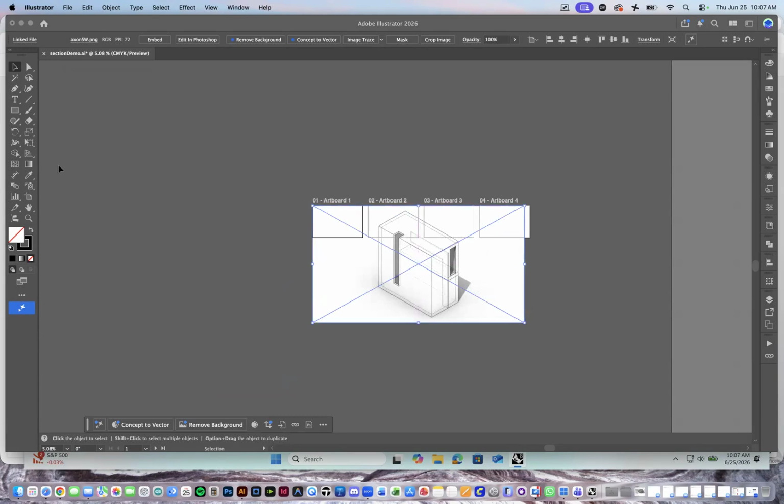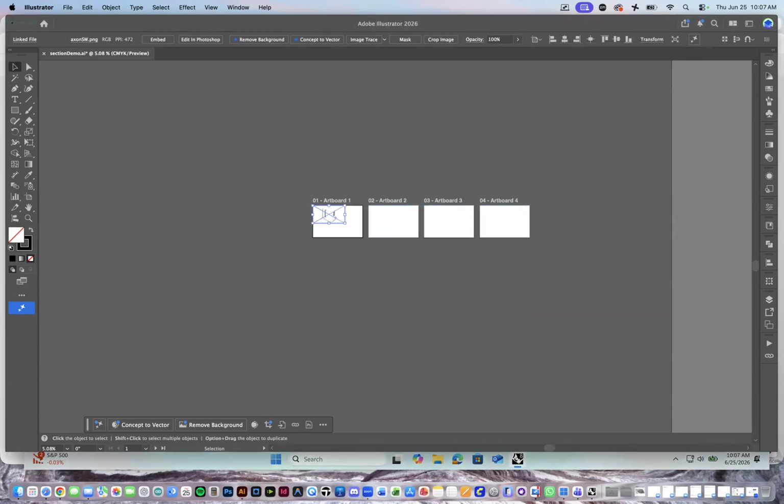I'm going to go ahead and let me just move this around. I know my document, my page size is 11 by 17. So with this selected, I can go to the transform up here. And now I can see that the size of this image is 72 inches long, 40 inches high. That's kind of extreme. I think I'll probably change this so that at the most it's only 11 inches long.